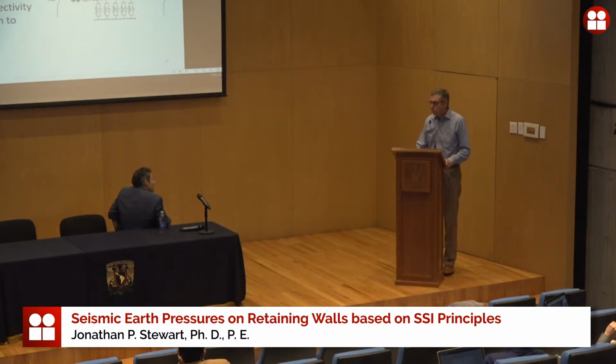So you still have the free field doing whatever it wants to do. That's unaffected. You have the hybrid of the two elements here, which would need to be taken into account in the flexural stiffness, obviously. Then you have a pretty significant axial stiffness, and you have some rotational stiffness associated with this pile here.